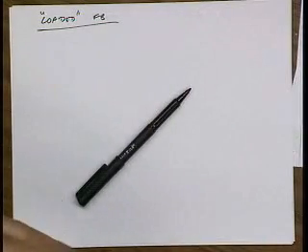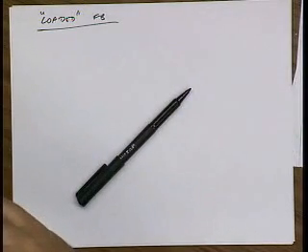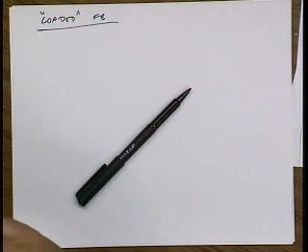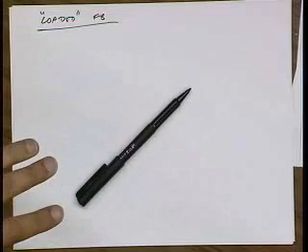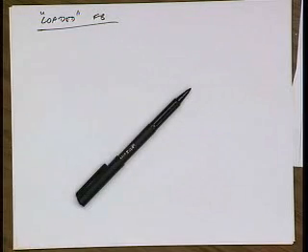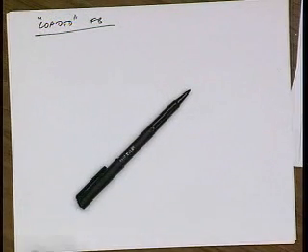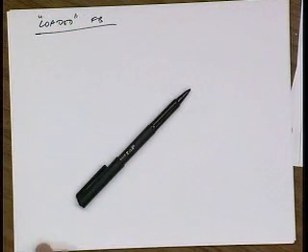Very importantly, the noise. Remember, before, when we talked about noise in feedback circuits, we came to the conclusion that if you can compute the loading at the input and just make that input loading noisy, that pretty much takes care of the noise of the whole circuit. As an approximation, but a pretty good approximation.